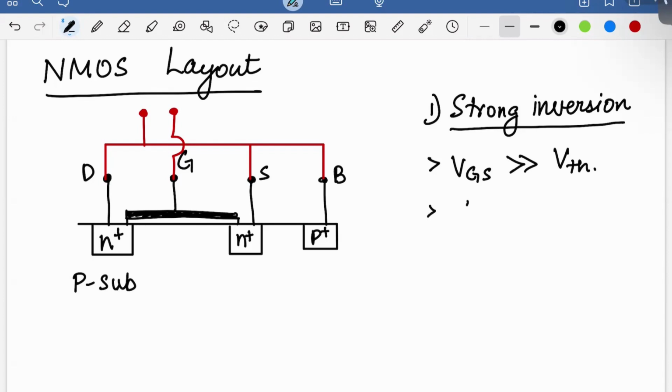So in this case, the capacitance, okay, so what actually happens, right? If I make VGS very large, then you have a channel that is created down here of electrons, right? And then of course you have, let's say, positive charges here, and that essentially forms your capacitance, right? So you have parallel plate capacitor between this region and this region. And since this channel basically forms right underneath the oxide, you can approximate very well this capacitance as just the oxide capacitance of this oxide layer.